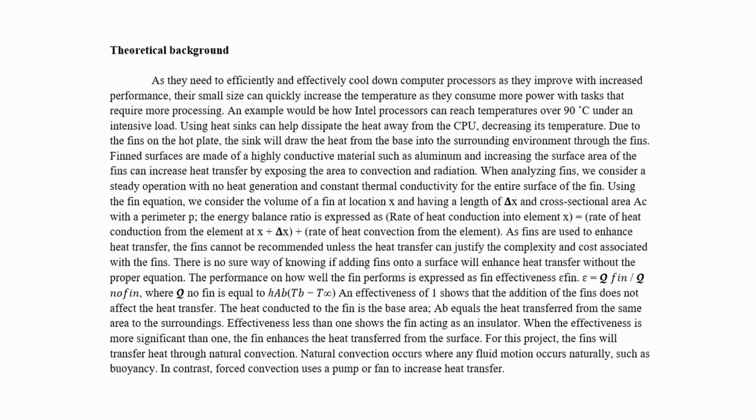For this project, though, the fins will transfer heat through natural convection, and natural convection occurs when any fluid motion occurs naturally, such as buoyancy. In contrast, forced convection uses a pump or fan to increase heat transfer.